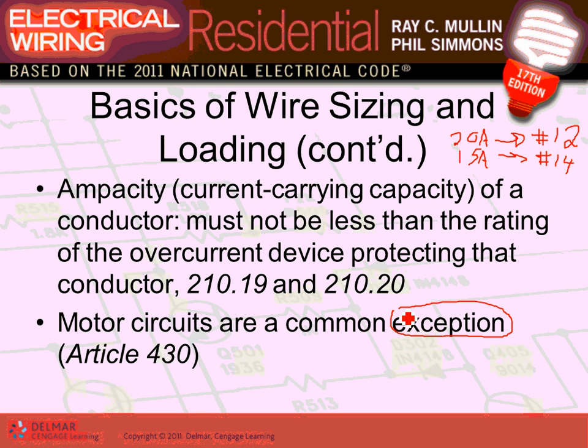So let me list the third one, because these are the most common. A 30 amp circuit breaker always goes with number what? Number 10. So number 10 gauge. So Karen, between 15, 20, and 30, you have just wired 95% of every load in every house. That's it. You know what's left? What's left is 40 amp.